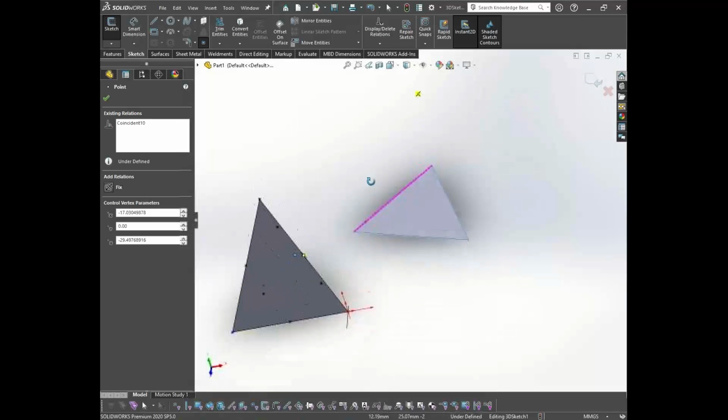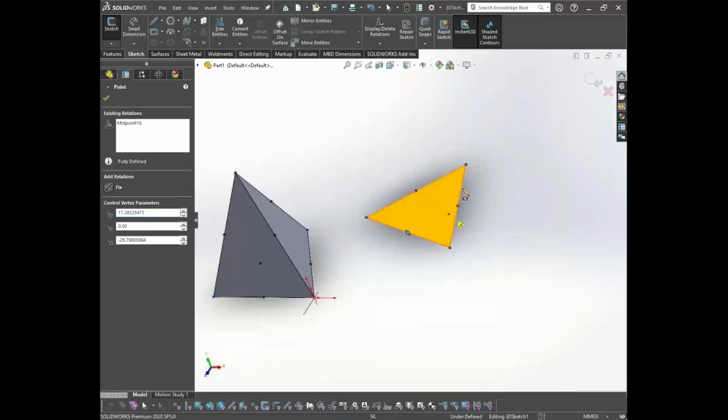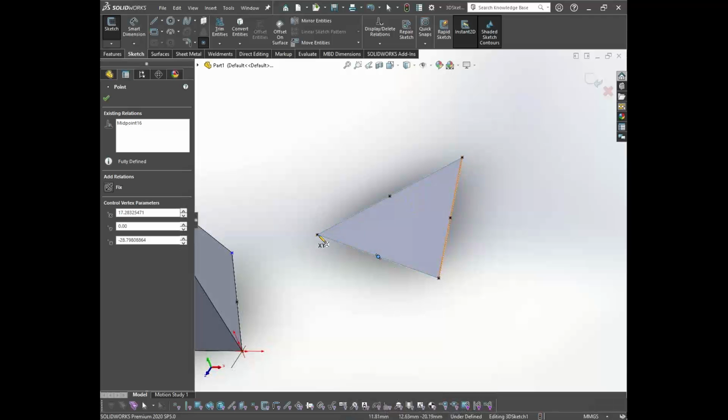Similarly, when we are dealing with the shell elements, it will have 3 nodes at the vertices. When I increase the order of the elements, the mid nodes are created here. So now you can see earlier it was only deforming at these 3 particular locations. After introduction of 3 more nodes, it is more easily deformable.